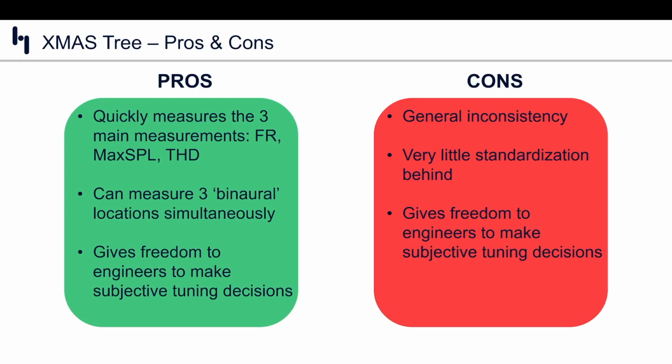Depending on who you talk to, the types of measurements and data you could capture varies. Currently, there's a technical committee in the AES that recommends you look at 3 primary measurements. Frequency response. This is the most common measurement in all of audio, not just automotive. It reveals basic properties of the system and can provide a visual indicator of spectral balance in the audio system. Max SPL. This is an important system-level spec that puts demand on the loudspeakers, amplifiers, and system as a whole.